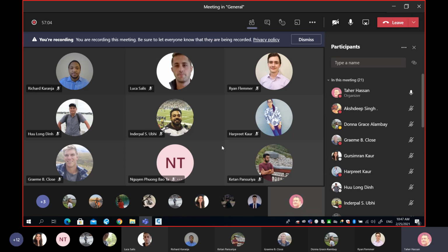I'll give you an example. Let's say you send your surveyor to the site on February 1st. And he or she gave you some points. And then you send them back on March 1st. And they give you another survey. I'm asking you, which one will be the base and which one will be the comparison? February base, March comparison. Thank you, sir. Exactly. So my rule is easy. The base is where you start. The comparison is where you end. That's the rule. Okay. Remember this.